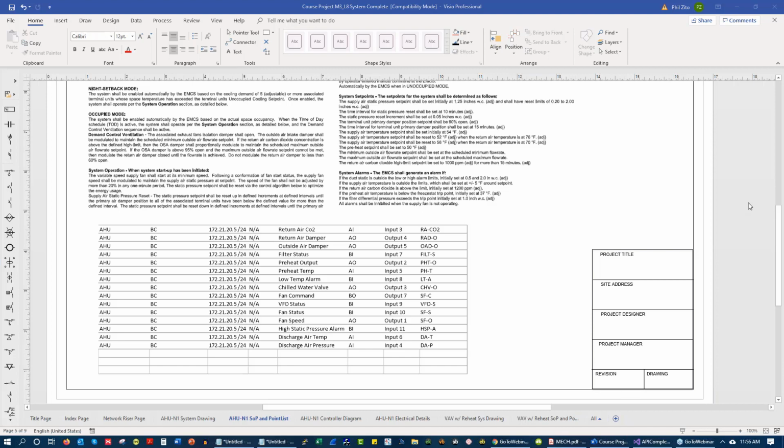So I almost always recommend virtual machines, because what that allows you to do is create a snapshot of the BAS install, so that if it fails, you can bring it back up right away. So that's why I recommend having a virtual machine.